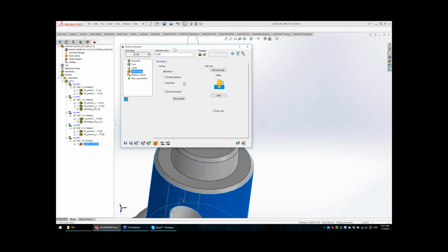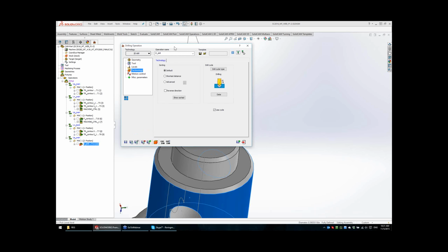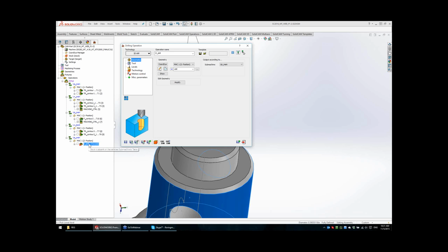I did this mistake by mistake. I didn't intend to do this mistake, but that's very good that I did it. In the start, I select the wrong submachine, upper turret on main spindle, but the stock is already on back spindle. So when I save and calculate, first of all, when you bring the mouse on the operation, you can see the red dot, red point.